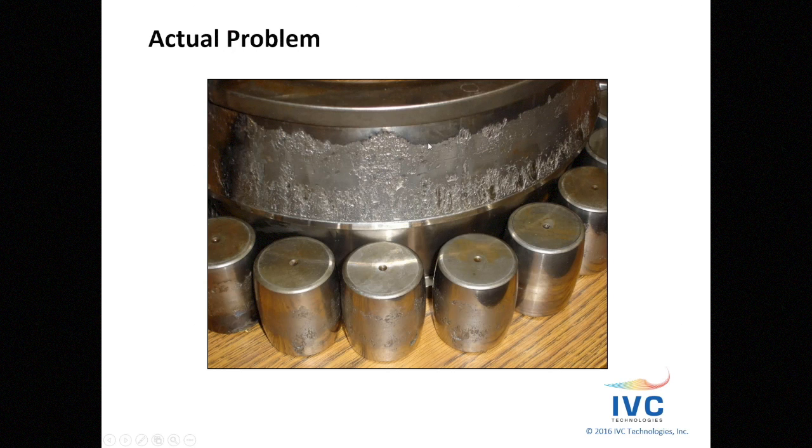So this was the actual problem, even though for 5 months prior to us being in the mill, they had been chasing or trying to evaluate a gear problem, and it wasn't a gear problem at all. It was a bearing problem, but it's because they didn't have the right mechanical information.